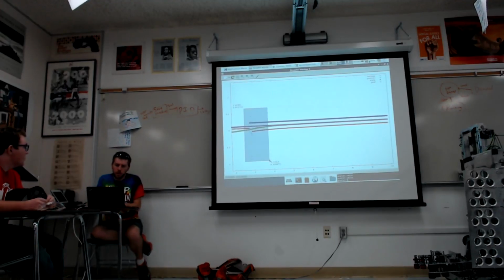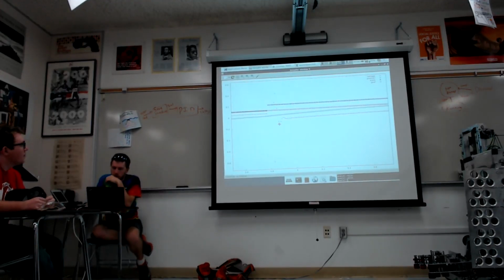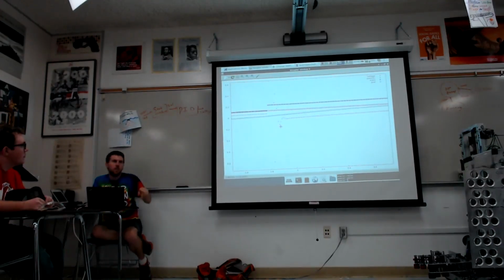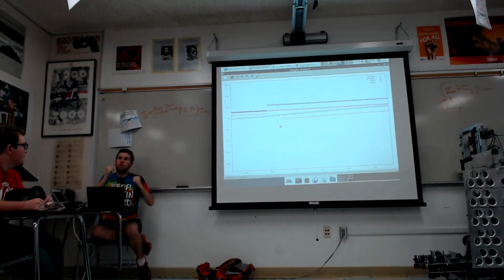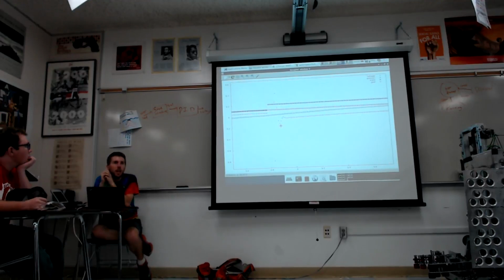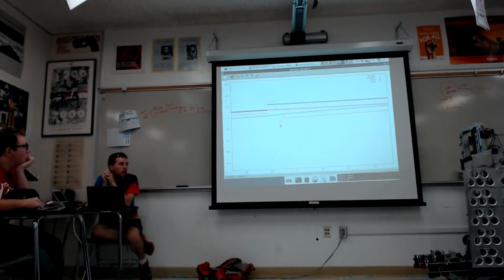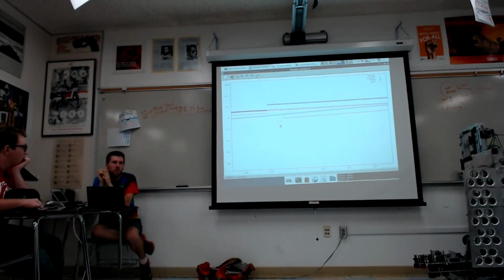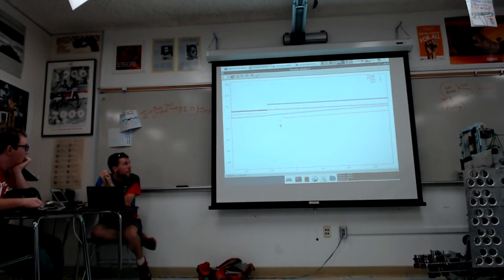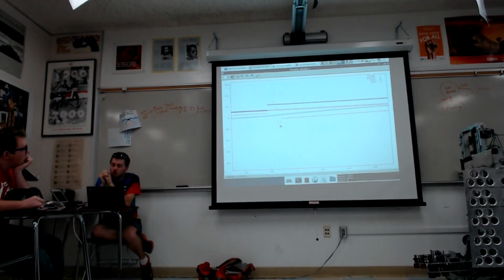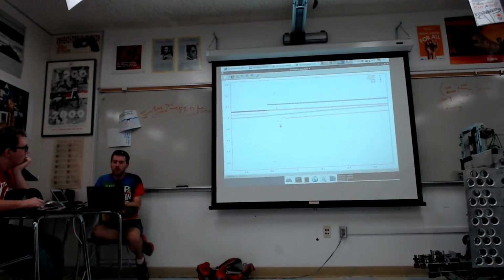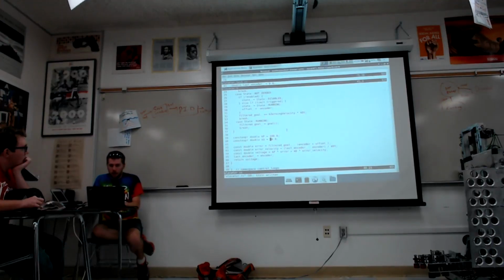This is starting to freak me out a little bit. So it's making a large amount of corrections. Like, this doesn't look very smooth. Yeah. We're continually second guessing and changing. Real hardware isn't as good as our simulation. It's going to do a little bit less of what we want, so we're going to amplify the noise. So I don't know if that'd be stable. I wouldn't try that. So we should slow it down, figure out why it's trying to do that. Probably means slow KP down a little bit.